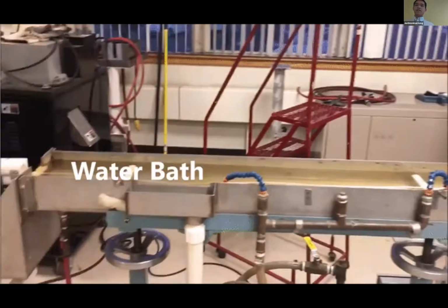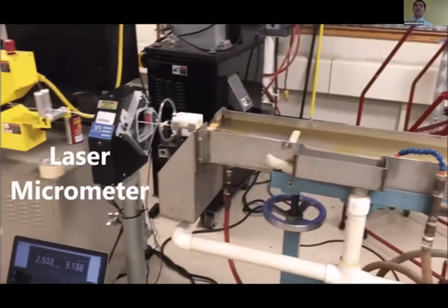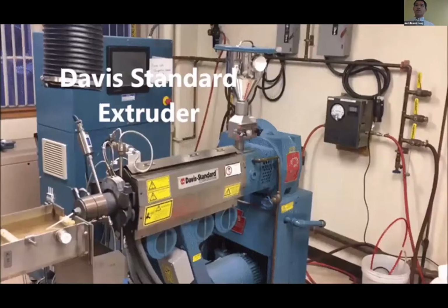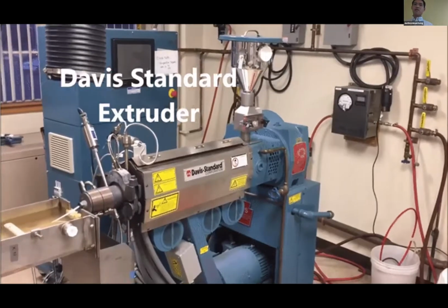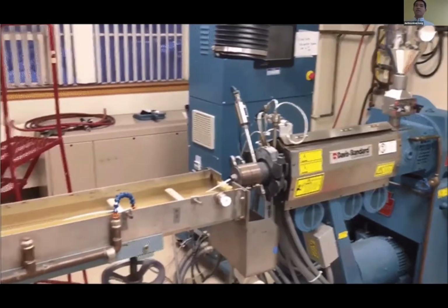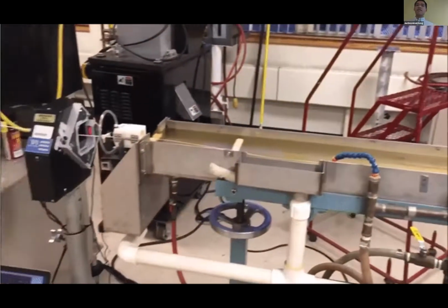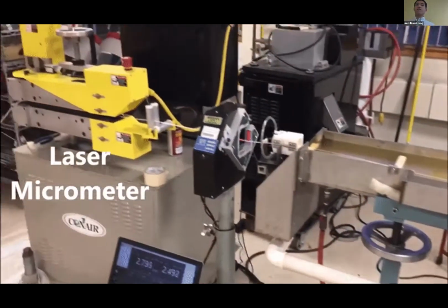So here's a quick video or GIF of the whole process of creating that filament. As you can see at the beginning, you'd see that Davis-Standard single screw extruder. It passes through a water bath, which basically cools your filament. And then through the laser micrometer and data acquisition system, which we hooked up in the belt puller.